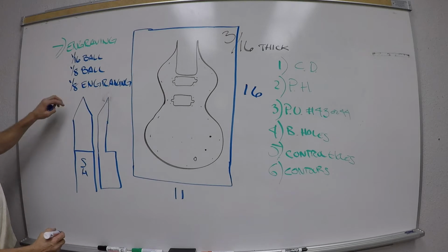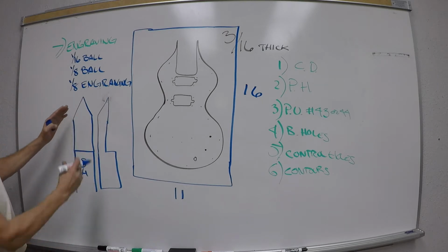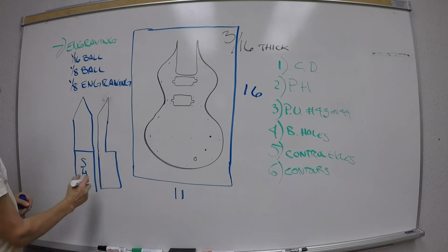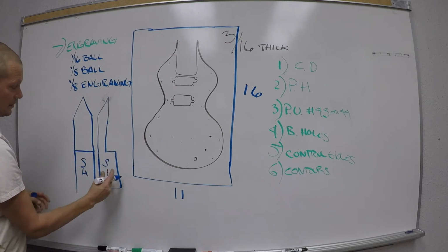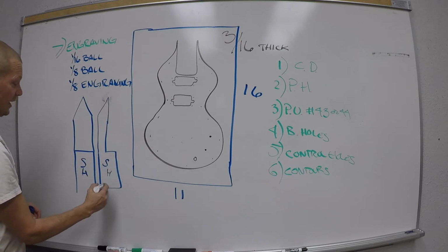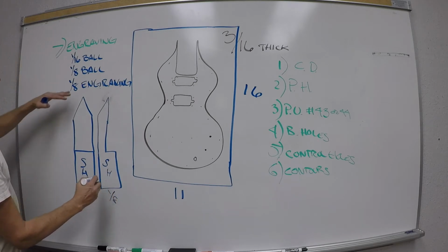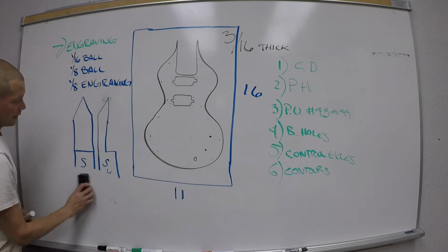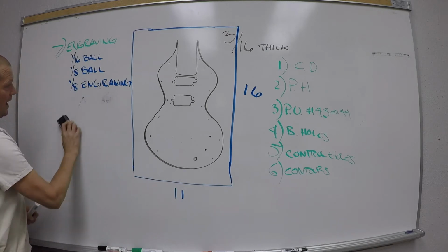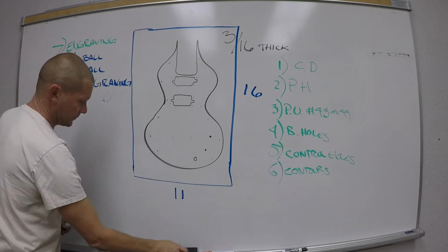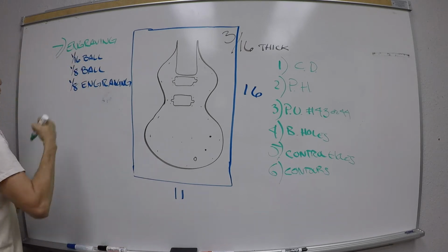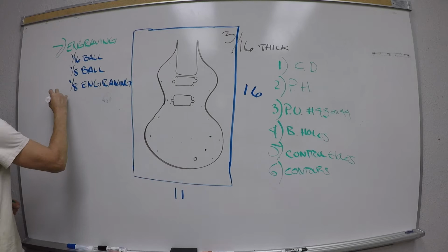Okay? So it's got a tip on it, but it's round to the tip, but it's flat. It's like cut in half. And then this is the shank, and it's round, okay? And this is an 1/8. So these three tools are, needless to say, extremely small, and they're going to be doing some engraving. After the engraving is done, I'm going to come in with a 1/4" end mill, and this is really what I want to talk to you about.